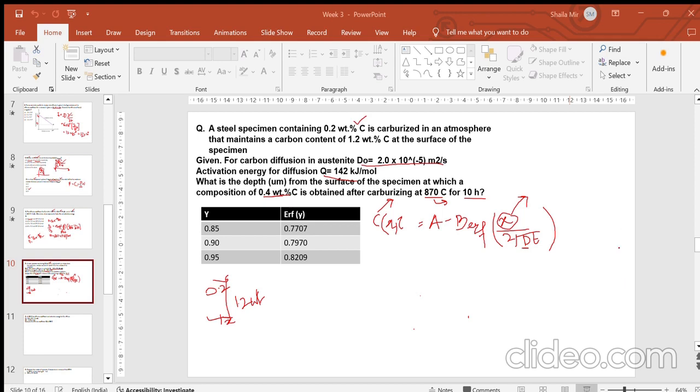Second, the eutectic point gives you a direct conversion from your liquid to your solid. There are no intermediates like alpha plus liquid or beta plus liquid phases. It is a direct conversion of your liquid solidifying into two solids, alpha and beta. Okay, so it says that it shows the composition and temperature at which the alloy undergoes a phase transformation. It illustrates the diffusion kinetics of an alloy's components.